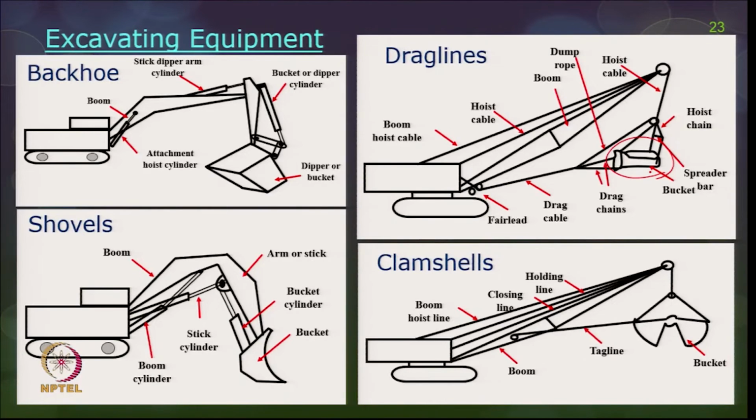In shovels, it will have a bucket or a grab which is away from the equipment, and drag lines are like, you can see, a tray or some sort of a setup through which it takes out the soil and does a lot of the dredging operations. Clamshells and drag lines are generally used in places where there is a water table seen, primarily in waterlogged